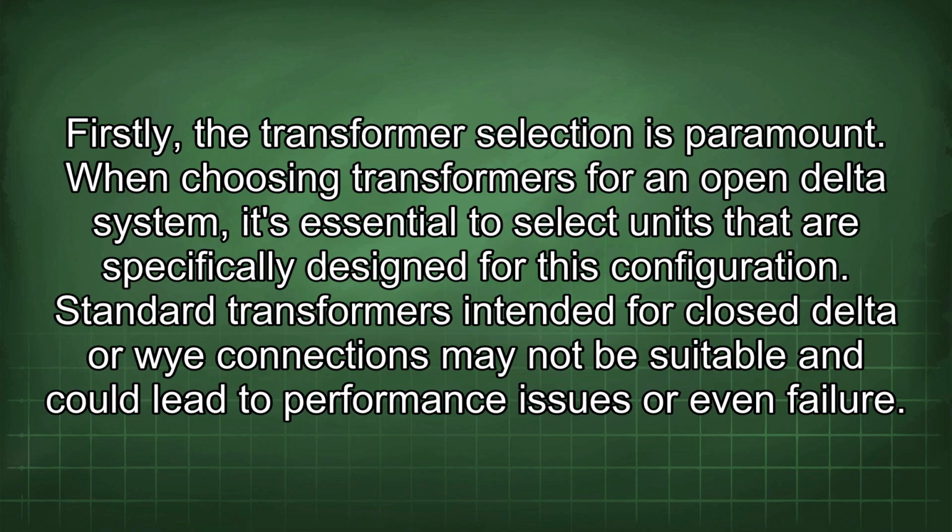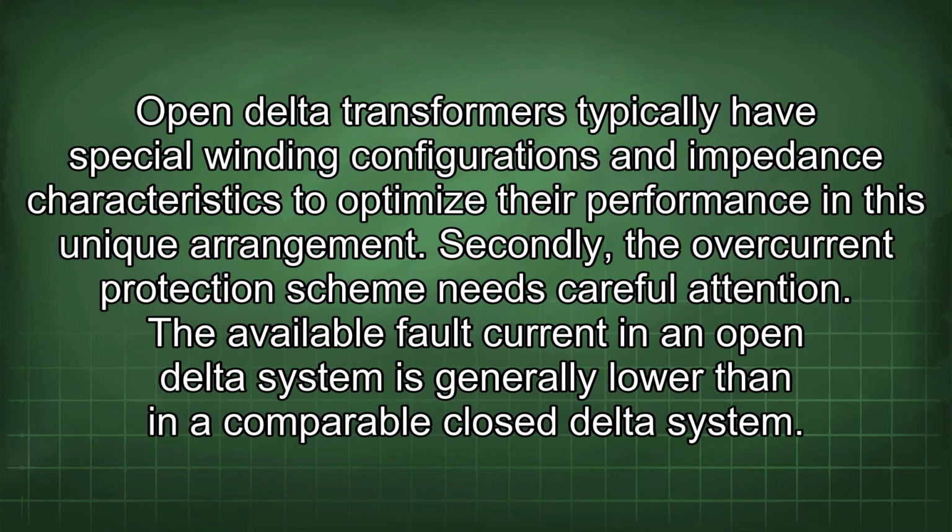Standard transformers intended for closed delta or Y connections may not be suitable and could lead to performance issues or even failure. Open delta transformers typically have special winding configurations and impedance characteristics to optimize their performance in this unique arrangement. Secondly, the overcurrent protection scheme needs careful attention.